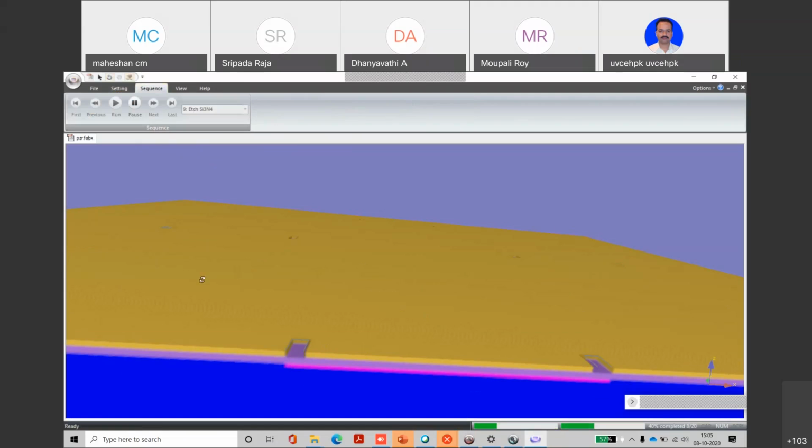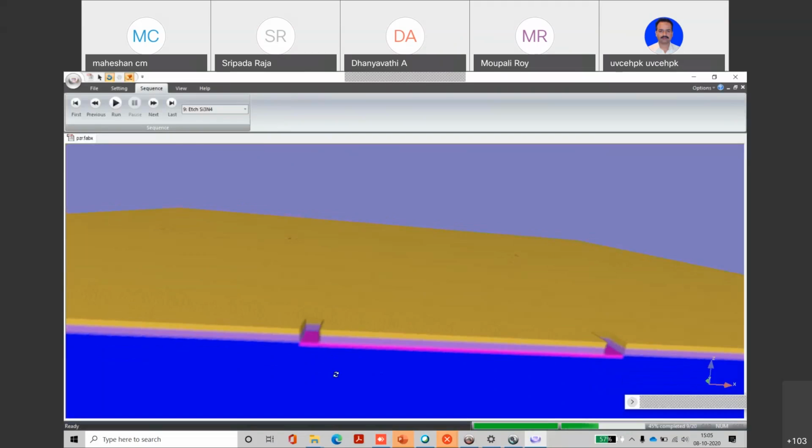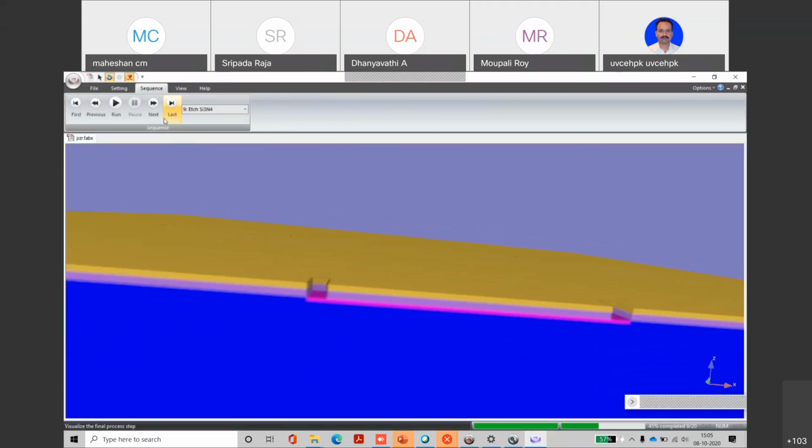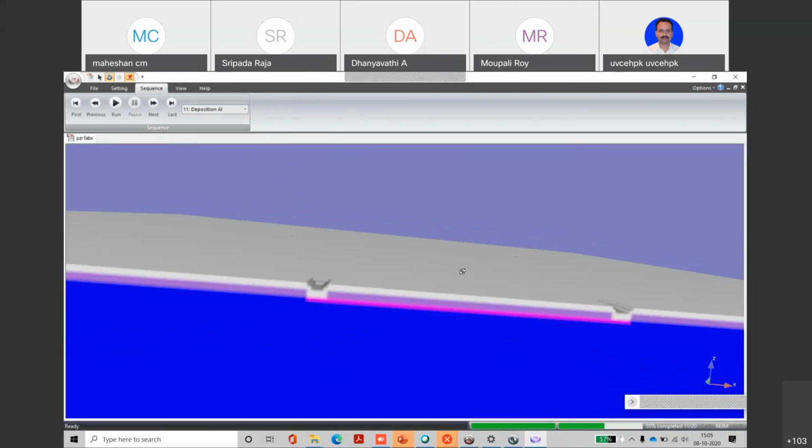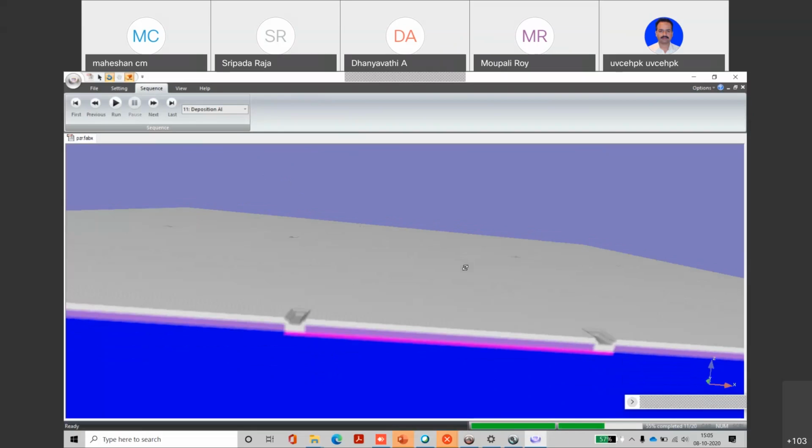You can see that we remove only that part of it. So it is like the wire bond is this. This is what we are trying to do, the via contact. Here we create a small opening and then we put a metal on that. So the resistors are connected via the metal.